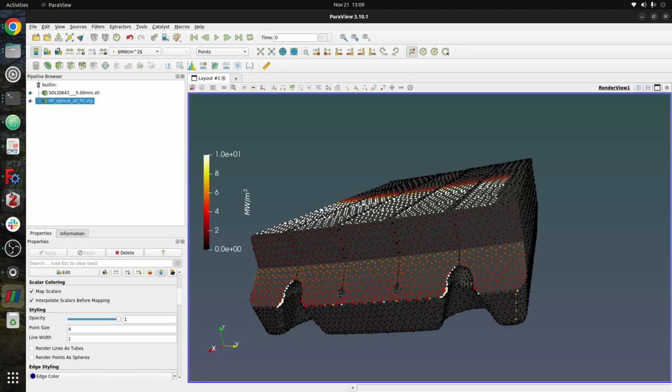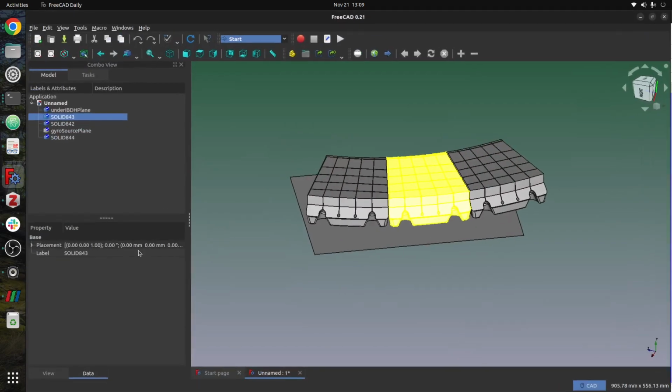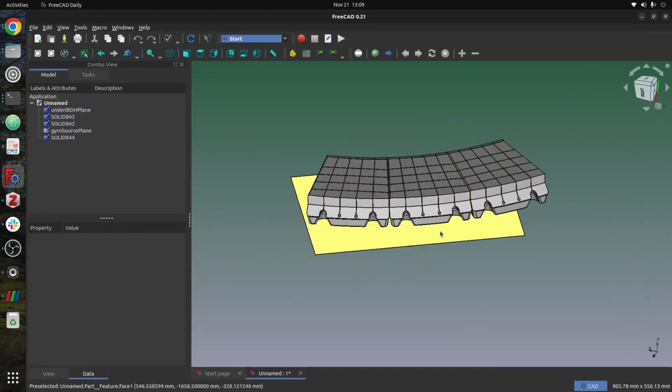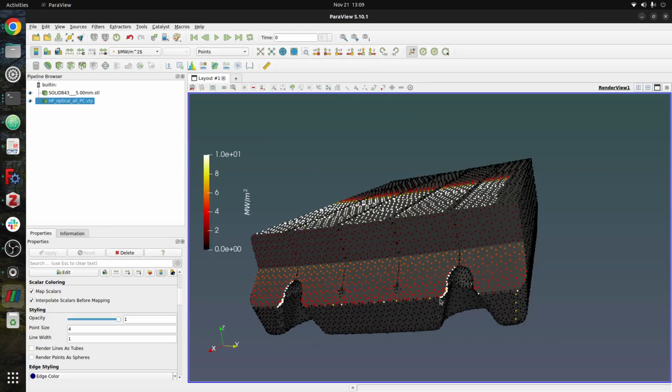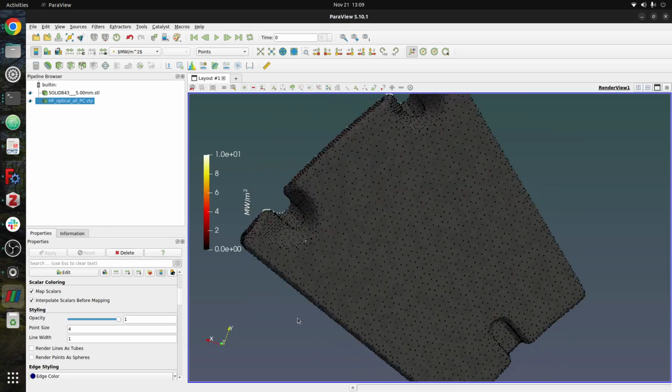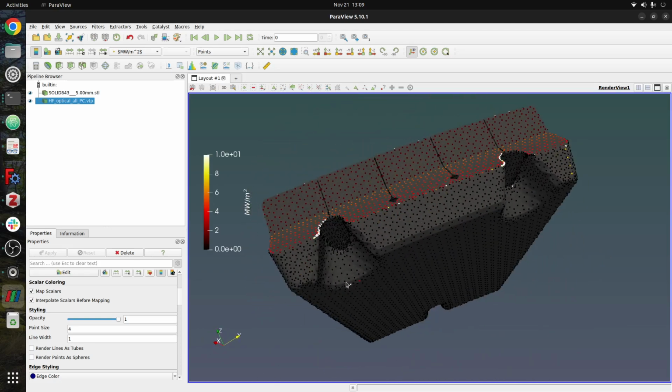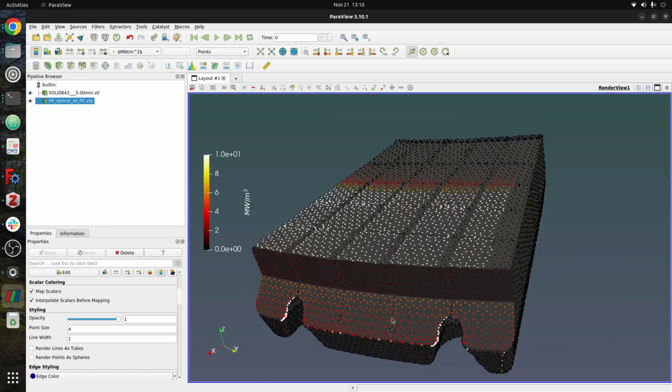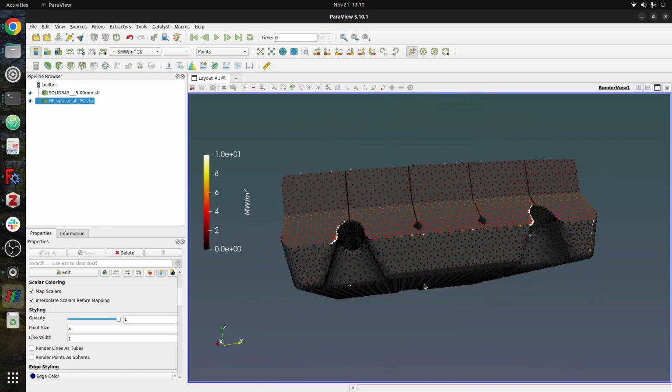That's because we didn't include the CAD objects that are right here. We only included one poloidal location of tiles. If we would have included the next tile over, that would have protected this. So you want to see that. That's actually good because it shows that we're not getting shadows cast there where there is no CAD. And we can see that the bottom is good. These will go away if you trace to 20 or something. So this looks pretty good. Something like this is what you're looking for.